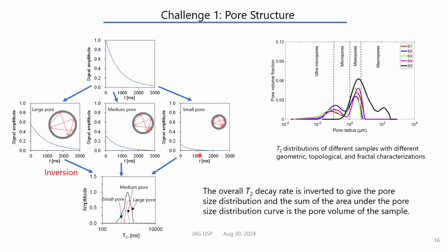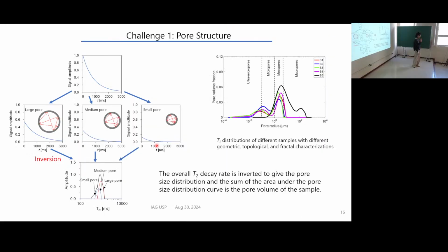And sometimes we have a bimodal distribution in the rock fracture. This bimodal distribution can have some pore structure at nanometer scale, and some pores at millimeter or even centimeter scale. And you see two very distinct peaks in your NMR relaxation time, one corresponding to very small pores, and another corresponding to the large pores. So I think this is a very useful and very intuitive tool to help us understand where your water resides.